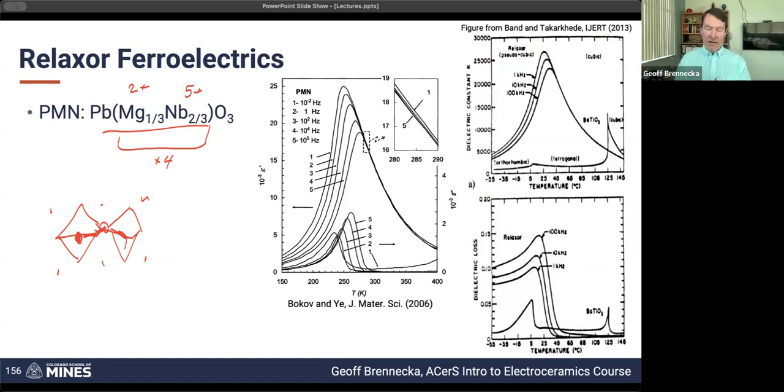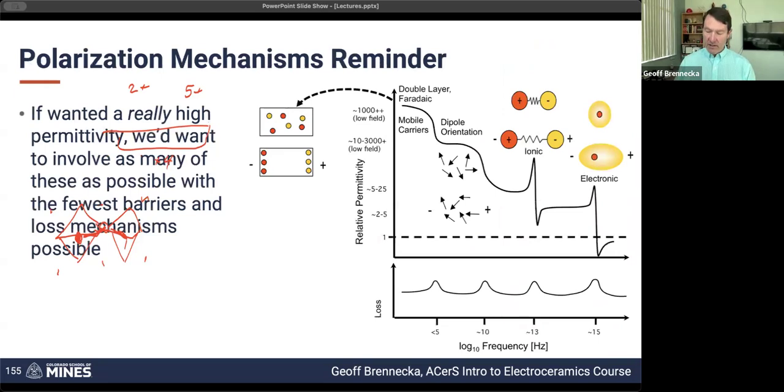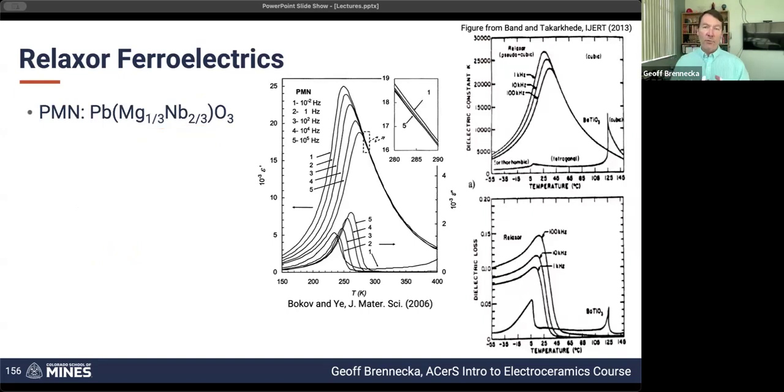And so because of that, the spring constants between each of these differ. If we think back to the polarization mechanisms plot, we're looking at the ionic aspect as basically being springs, and then from that, we're developing these spontaneous dipoles. So we've got different spring constants all over the place. And if we look at the spontaneous dipole locally, let's go back to that octahedral model.